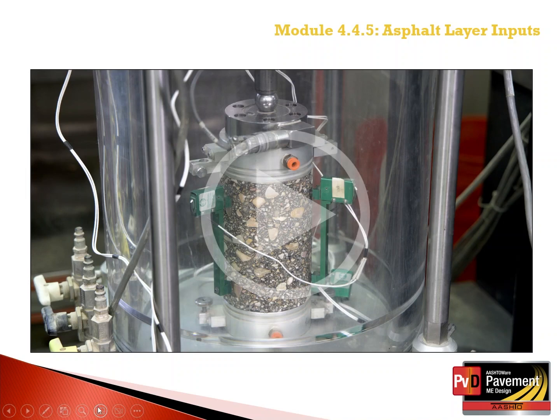The dynamic modulus measured on an unconfined test specimen, as illustrated in this video, will be consistently less than the dynamic modulus measured on a confined or triaxial type specimen. As such, the condition of unconfined and confined should not be mixed to ensure input compatibility.